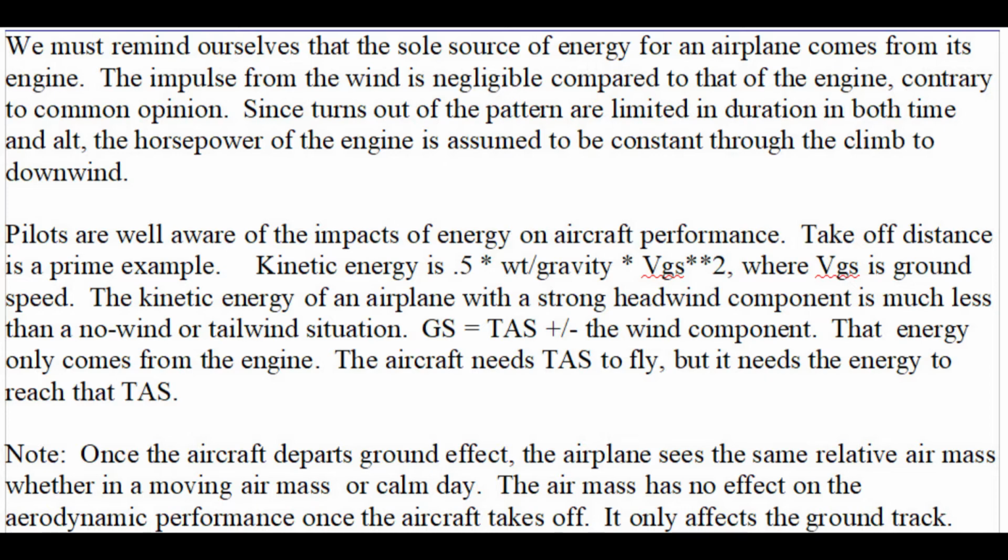Since turns out of the pattern are limited in duration, both time and altitude, the horsepower of the engine is assumed to be constant through the climb to downwind. Pilots are well aware of the impacts of energy on aircraft performance. Takeoff distance is a prime example. Kinetic energy is 1/2 times the weight divided by gravity times VGS squared, where VGS is ground speed. The kinetic energy of an airplane with a strong headwind component is much less than a no-wind or tailwind situation.